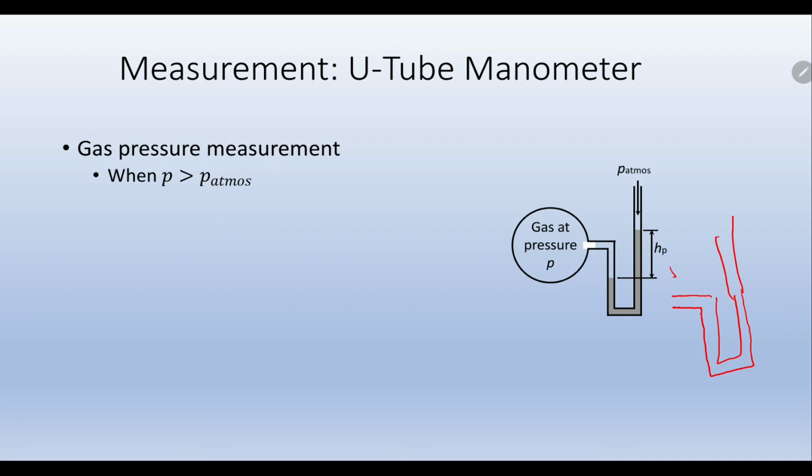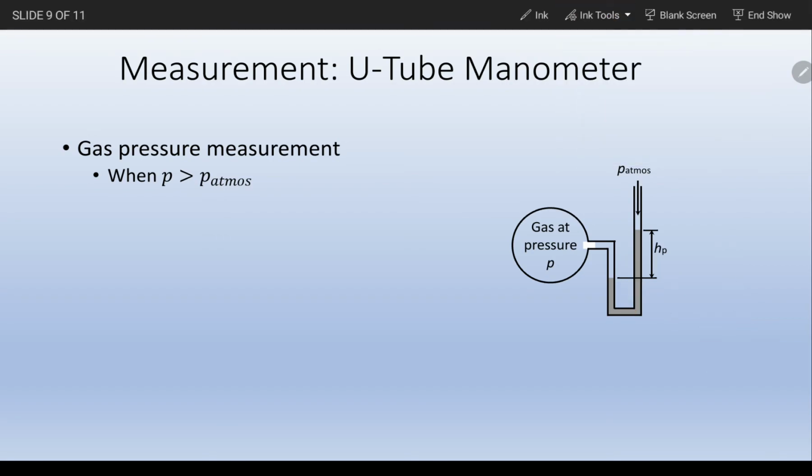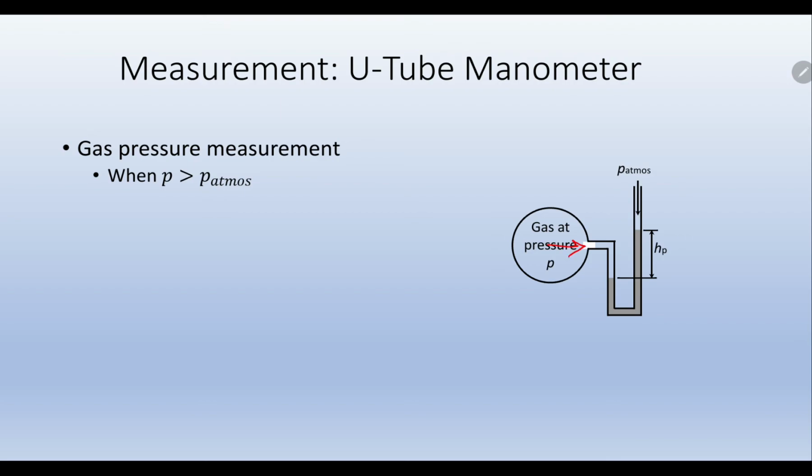And then here you can actually blow air and measure the pressure that you are exerting. Usually it is filled with water or some manometer fluid or mercury, though nowadays not mercury anymore. When you blow air, you are increasing the pressure. So what do you think will happen? This fluid will go down and this fluid will go up. So the difference in the height, my dear people, similarly, if I'm blowing air here, this layer will go down and this will go up.